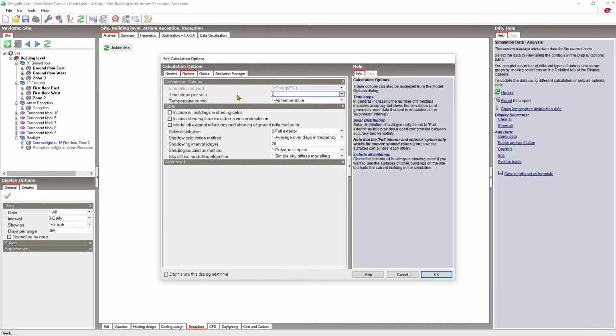You can select the most appropriate control radiant fraction from the temperature control drop-down menu. The different options can give significant differences in results, and using operative temperature control usually leads to higher peak loads and heating and cooling energy consumption. A useful discussion on the differences between air and operative temperature control is also included in the program help.